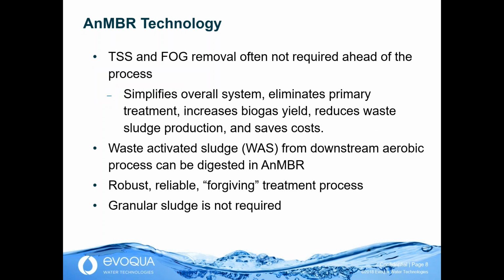A couple other benefits of the anaerobic MBR is that often wastewaters with high concentrations of TSS or fat, oil, and grease are good candidates for anaerobic MBR because these components can be challenging for conventional anaerobic treatment technologies. One benefit of the anaerobic MBR is that these components don't need to be removed upstream of the anaerobic MBR. They can be fed directly to the anaerobic MBR with minimal upfront treatment. We don't need to necessarily remove them. So this really simplifies the overall process and can eliminate the need for some treatment steps altogether.